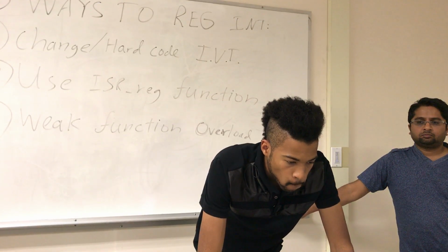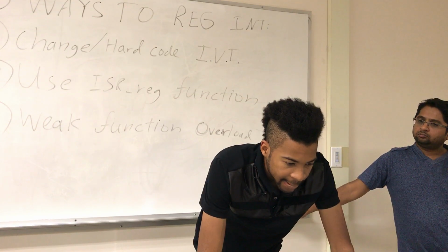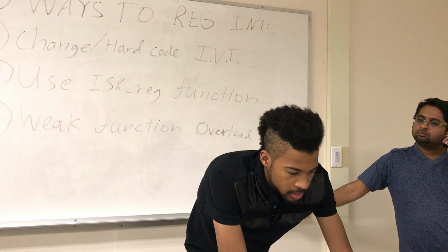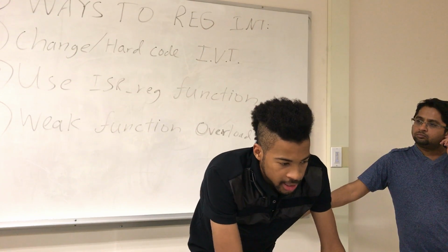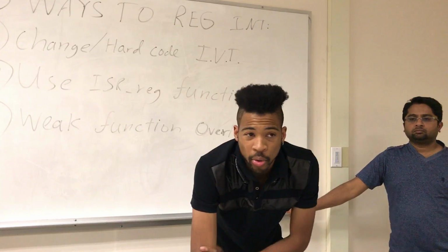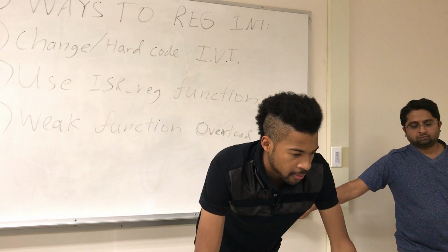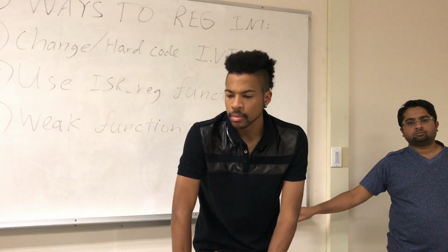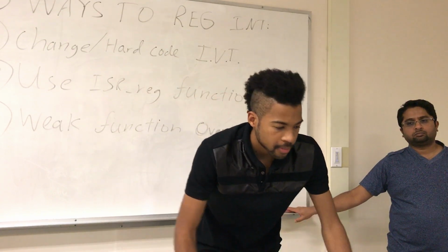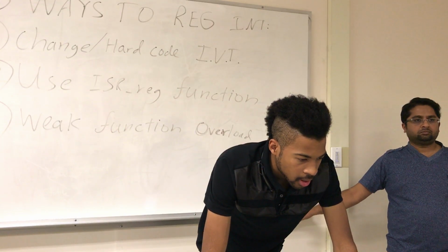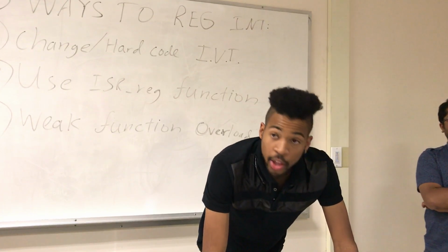But for this lab, we should just be configuring the pin that we want to use as the interrupt as a GPIO. Yes, it's all GPIO here. Don't worry about UART interrupts, don't worry about SPI interrupts. We're just looking at GPIO. Any other questions?